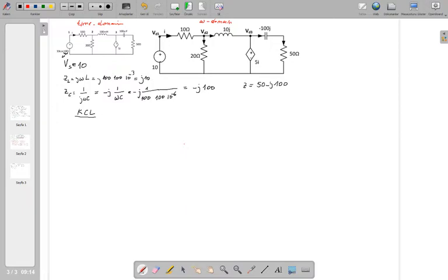So after I remind you all, we are going to write the Kirchhoff current law equation for the first node. Before we start, the current reference of this independent voltage source is downwards. The reason is passive sign convention is known. So okay, what is this current? Is IS, let's say, independent voltage source current phasor. That's why this is capital I. It's not time domain current. This is frequency domain current.